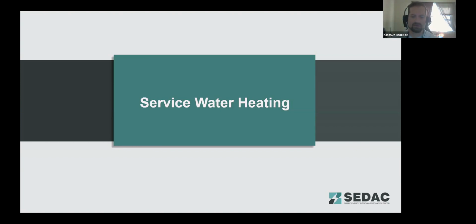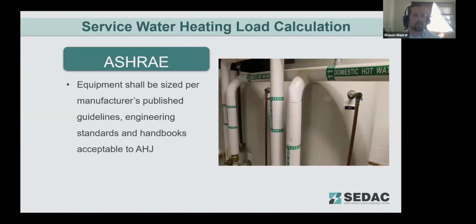All right, so looking at our service water heating requirements, we'll touch on these. For service water heating, ASHRAE does require a load calculation to be done to size the water heater. That's not included in the IECC. So similar to the building HVAC system, it's important to size the service water heating equipment properly to maintain that peak efficiency. Oversized equipment is going to lose that excess heat to standby losses and to losses out the vent stack for gas equipment.